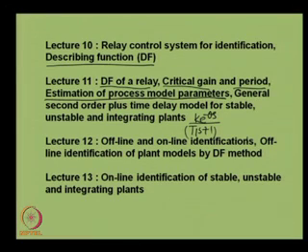first order process model. Similarly, we can have a second order plus time delay model for the dynamics of stable, unstable and integrating plants, that can be given as k e to the power minus theta s upon T1 s plus 1 times T2 s plus 1.